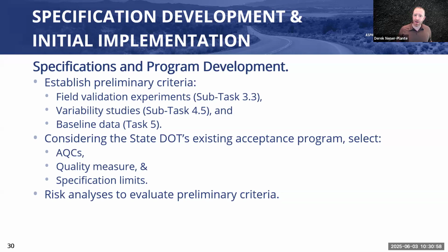A couple tenths, 2-3 tenths out of 4 to 5%. Right? We're talking about, with balanced mixed design, coefficients of variation of 20%. It's a completely different scale there. So it's something that's going to have to look different, be a little bit different, and be handled differently to be successful. So variability, you've got to know your variability.